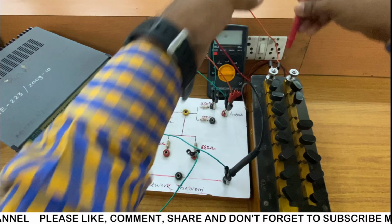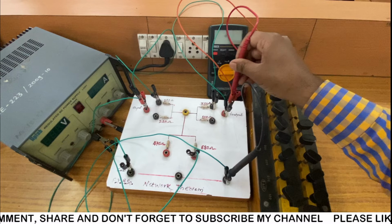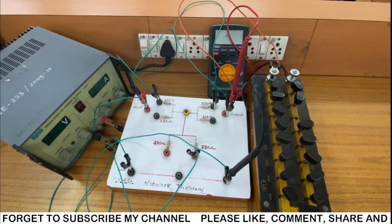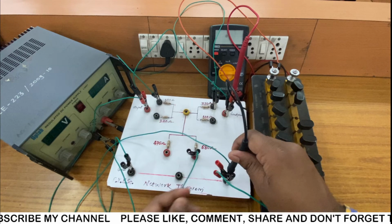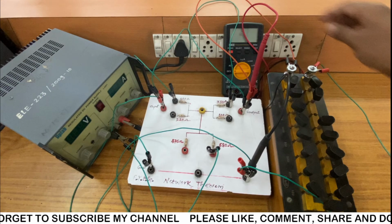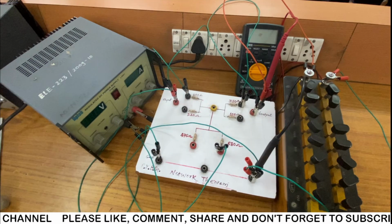First, the resistance box's first terminal, we can put in the resistance box or we can put at the V output, that is in parallel, so we can put wherever we want, the multimeter's positive terminal. Then the negative terminal we can put in the ground terminal or we can say the resistance box's next terminal. So this is done. The precaution to be taken to perform this experiment is that one key from that particular resistance box is to be removed. So I have removed one.